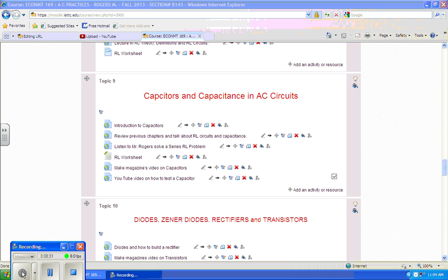Now, if you have somewhere near a meg ohm and you have somewhere near 1,000 microfarad, you're going to have a good solid time that you can look at. Well, we won't talk about how long because that's what you're supposed to figure out in this project, right? So, do you have to have an exactly 1,000 microfarad capacitor? No. Do you have to have an exactly meg ohm resistor? No. Do you have to have something close? Yes. Now we have 1,000 microfarad capacitors in the lab, so that's not a problem.